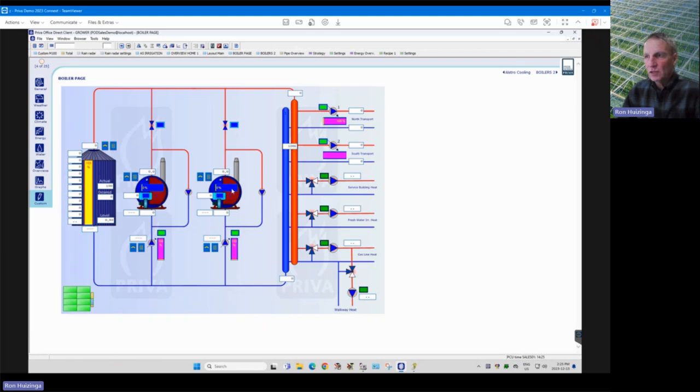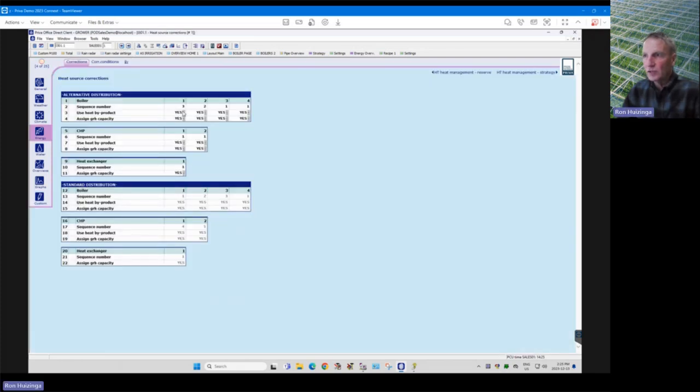So typically it's thought to be more efficient to run 2 boilers at 50% than 1 boiler at 100%. So if your boilers are all identical, then the typical thing is you run them all at the same priority, the same sequence number. But if you have 2 boilers that are, let's say newer boilers and have condensers, and some boilers that don't have condensers on them, then you'd make a different priority system for them.